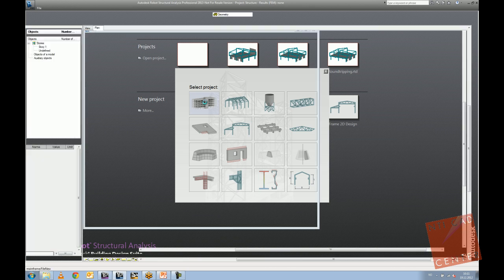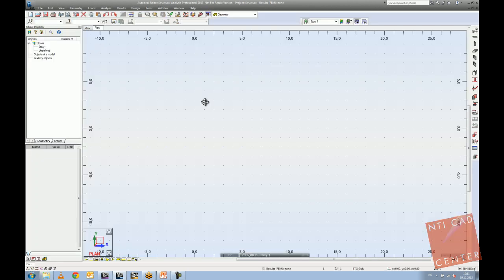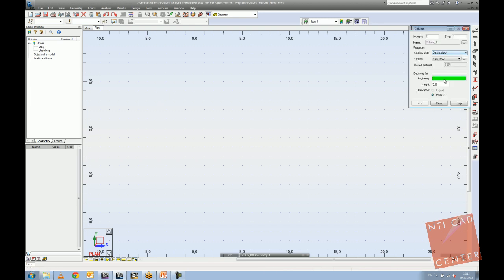And it works in a way like Revit does. So you have plan views and then you have a general view. In the plan views, you're able to model elements, for example columns. If I draw a column, it is just one point which I specify, and then you say whether it is going upwards or downwards, and what the height is. So basically, you're standing in a plan and you're modeling by drawing walls and columns and everything.